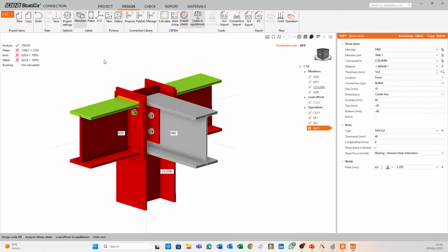And what we would then normally do is go back and make some minor adjustments to the size of our end plates or the thickness of our fin plate, etc. But in general, under these circumstances, we would increase the size of these members, even though this member itself might be passing all of its checks with flying colors, right? So if the actual utilization of this member was maybe 50%, but now because of this connection we have to upsize that member, that can be incredibly expensive because this member could be quite large, right?